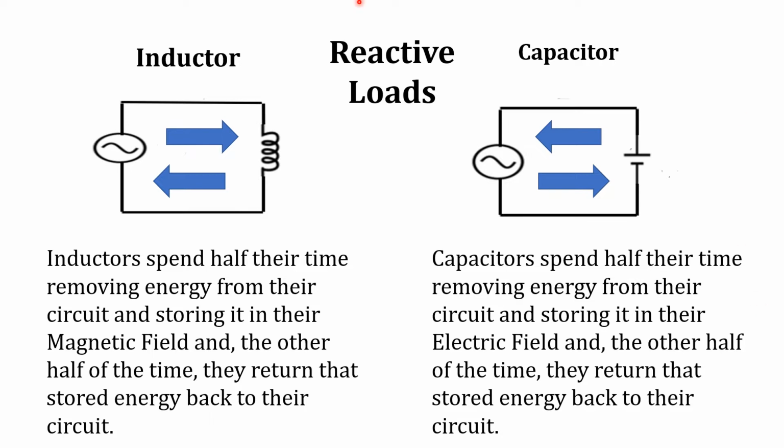True to their name, reactive loads, such as the inductor and the capacitor shown here, spend half their time removing energy from their circuit and storing that energy in their fields, a magnetic field for the inductor and an electric field for the capacitor. And the other half of the time is spent returning that stored energy back to their circuits.